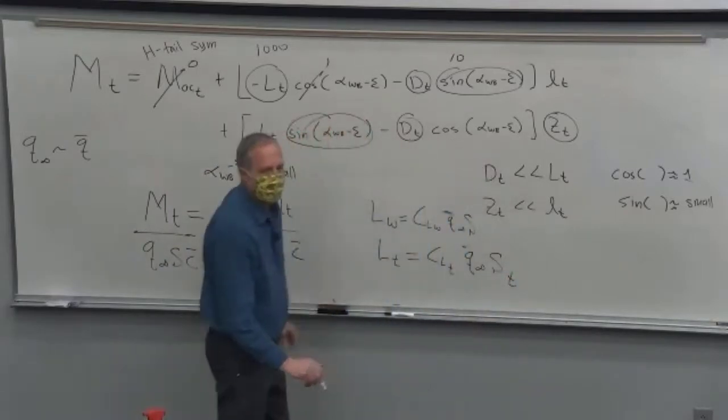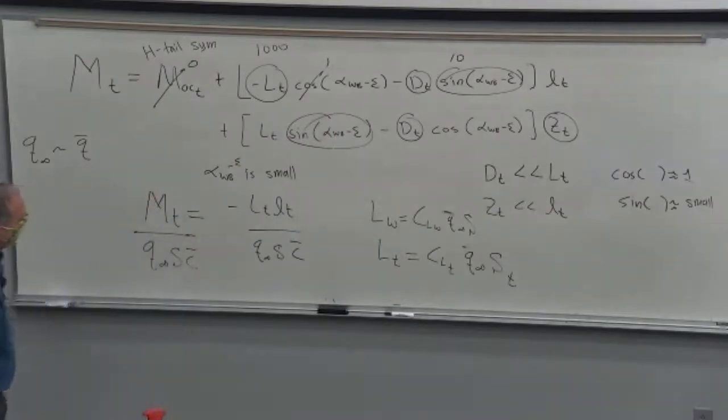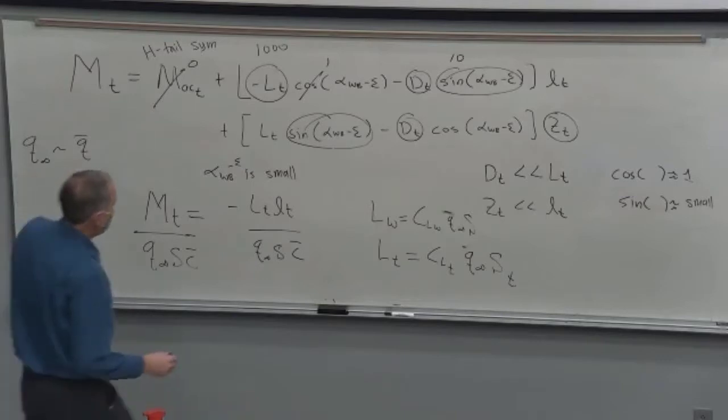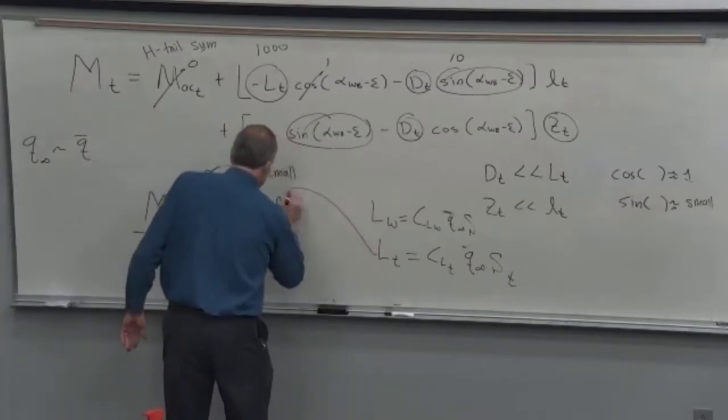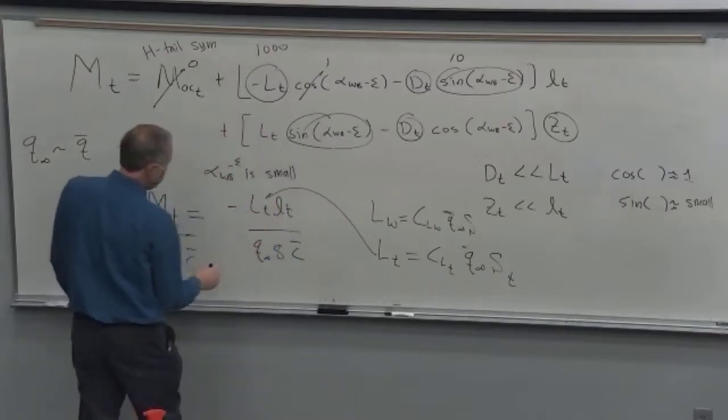Totally messed up my whole argument there. Because the lift of the tail depends upon its own area, not the area of the wing. The wing is totally independent. And so we have to use the tail area in here when we turn this into a coefficient.